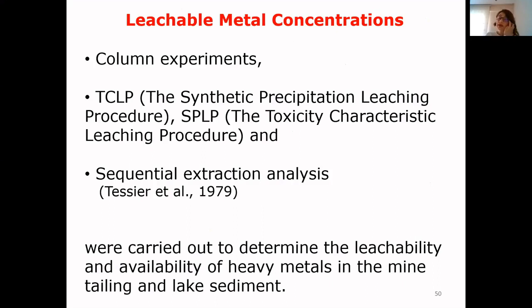And again, to understand the leachability, bioavailability, and the metal speciation, we did column experiments. And in this project, we did also TCLP and SPLP methods. Also, we performed the sequential extraction analysis based on Tessier et al. 79.